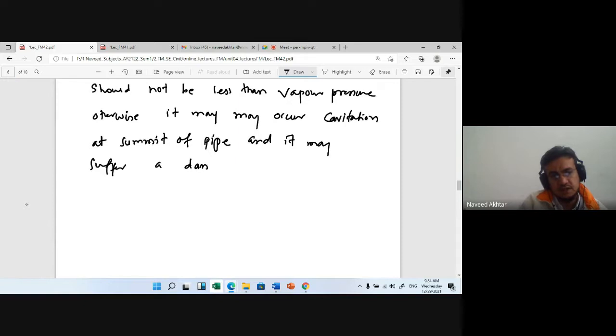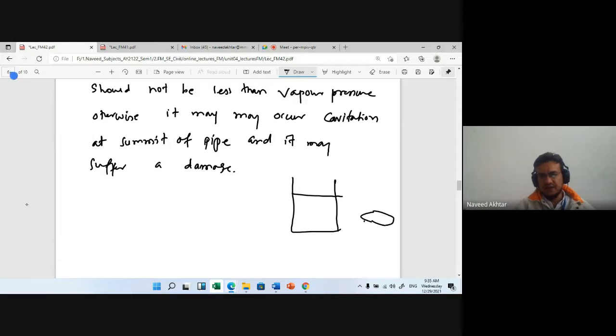So generally, siphon, when we transfer water between one reservoir and another and there is some obstruction in between. You might have seen that from a drum you have to take water out into a bucket. This is your drum, this is the water level, and you have to take out water, there is no pan, so we need a pipe for transfer of water. Okay, and this should be submerged deep into the water. Then we will create a negative pressure, and the water will flow over this summit. And this area is nothing but under the siphon action.